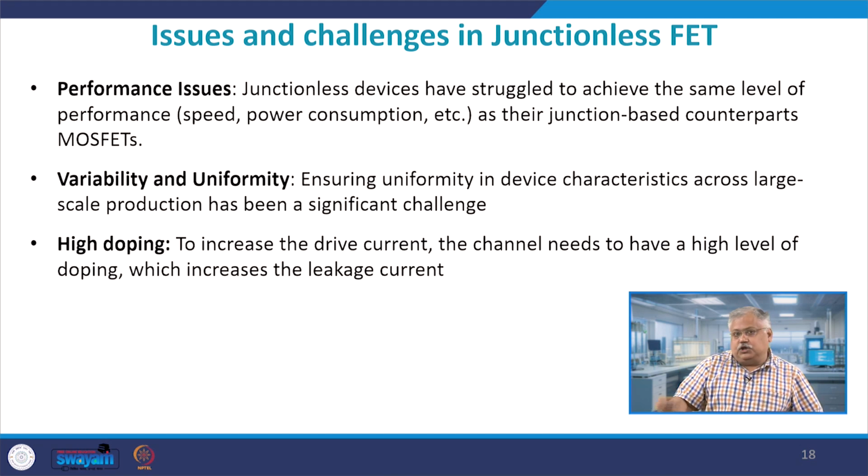But let us see what are the issues and challenges in a junctionless FET. Obviously there are performance issues, because though we are supposed to reach that speed, we are not able to reach it. Then there are large issues with variability, right? And that is a significant challenge, because as we have seen, the junctionless FET can operate very well provided you maintain uniformity and non-variability in your production process. But that is not the case. There is always an issue of variability coming into the picture, which degrades the characteristics of a junctionless FET device.